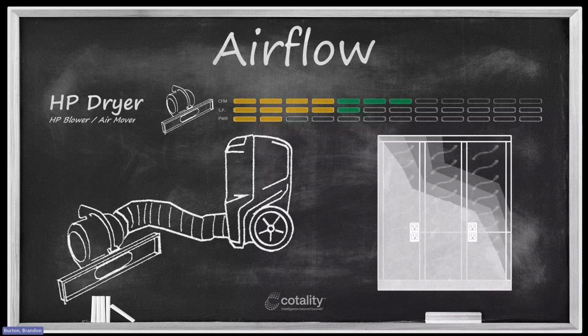You don't really need high pressure because there's not a lot of resistance. It's like getting rid of the coffee straw and replacing that with a 7-Eleven Slurpee straw. The air moves much more easily, so you don't have to pull or blow as hard to get a lot of airflow. So in a case like that, you want a blower that has the capability of delivering a lot more airflow, but it still needs to be able to do that through an attachment.